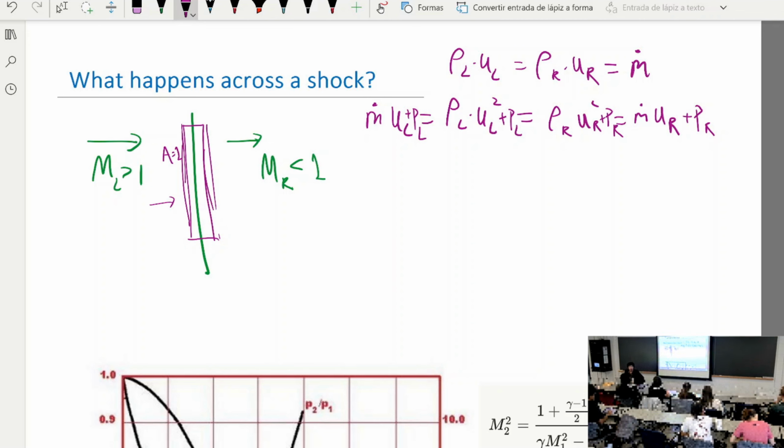So across the shock, density increases, pressure increases, but not isentropically. You cannot follow P equal to rho to the gamma power, because that's an isentropic relationship. It doesn't work over here. Although qualitatively the relation is the same, density increases, pressure increases, quantitatively the isentropic relation is wrong.